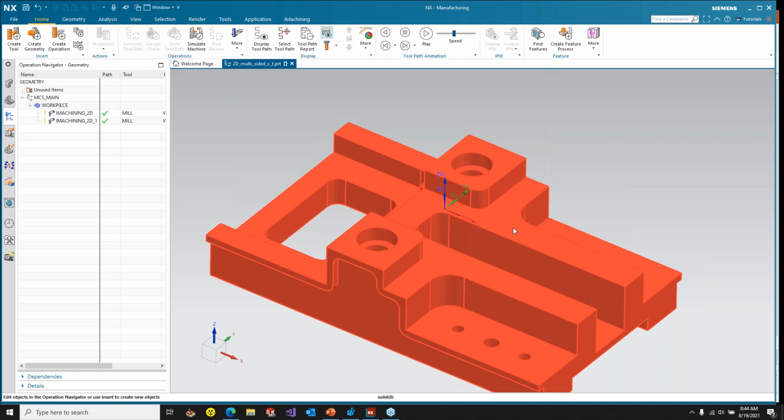Now, when we looked at the 3D iMachining part that I demoed here, if you wanted to work from the outside, you would have to pick smaller depth of cuts. That way you could start cutting away some of it. But eventually you're in a cavity, and that cavity you need to do helical entry. There is an option in 3D iMachining to ignore closed pockets. This is an option we added, I think maybe 2 years ago in iMachining 3D. So if you have a tool that can't support helical entry, you can turn off closed pockets, and it'll machine everything it can without doing the closed pockets. And then you could just go add another tool that can do helical entry.